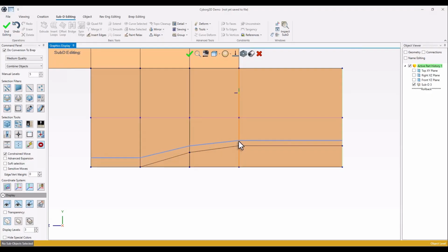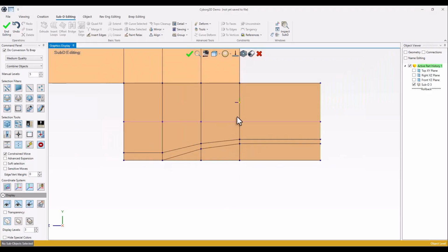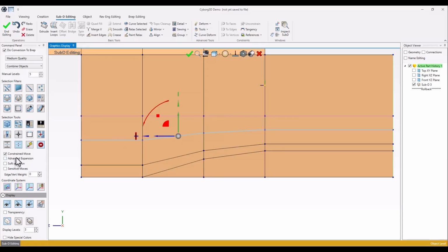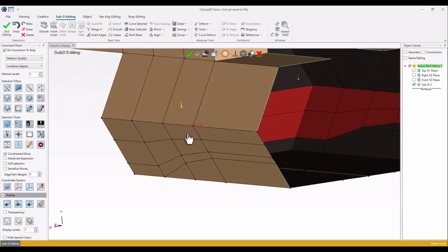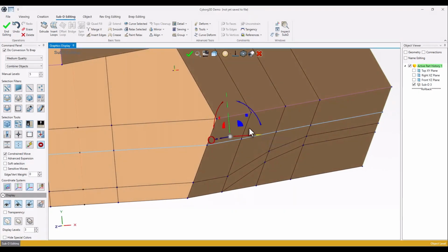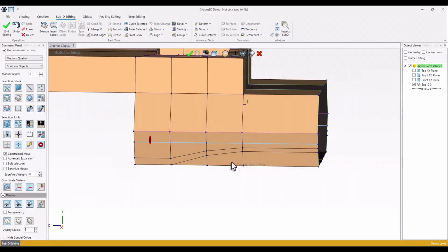You can do it by holding the A key, which is gonna follow the inserting edges I just did, and from here it's gonna follow also this one, so you can see it's just taking the shape of the nearest edge here. However, I can also get something in the middle. I'm gonna select my constraint move like this, and I'm gonna move my edges with the arrow like that, so it's gonna give me a very flat edge. You can do it again until it's just perfectly flat, depending on what I actually need.